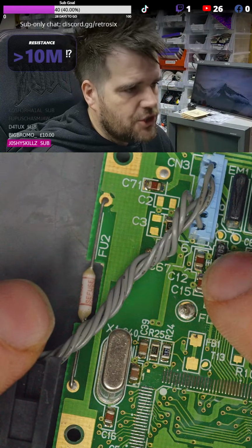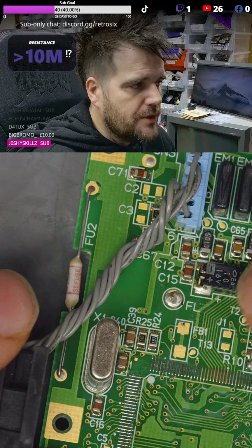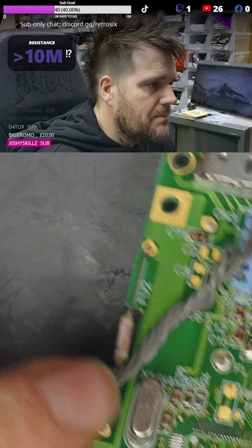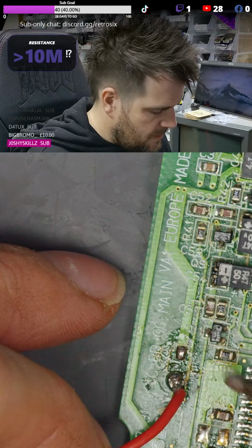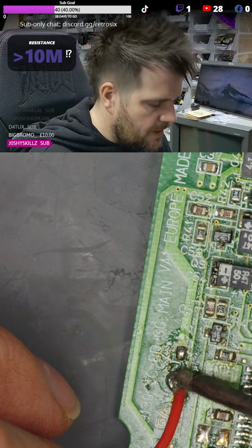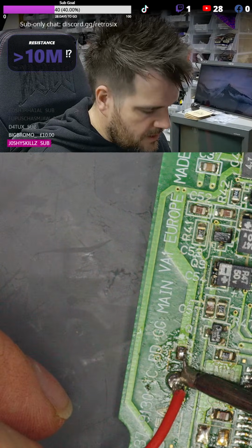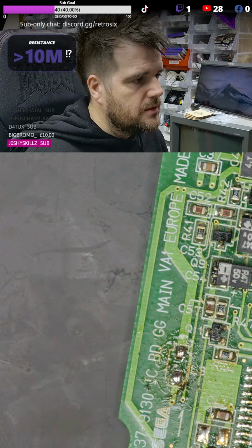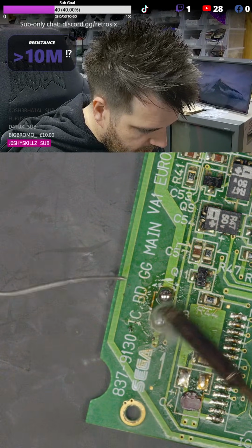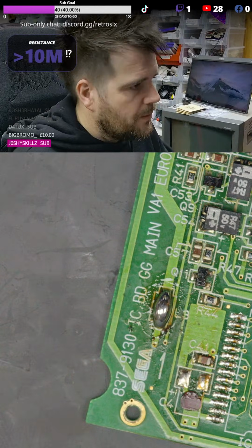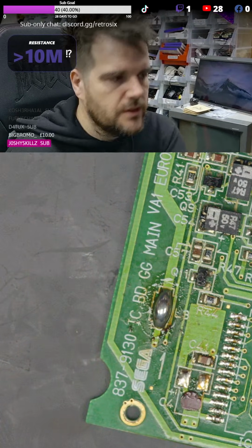If you don't have a dead short, though, thermals will almost always point you in the right direction. Just be mindful of things like the inductor getting hot. So I'll show you another example of another potential thing to look out for, a problem you should really be aware of. If I bridge this back, so I'm going to bypass the inductor, we don't really care for now, just put a giant bridge on. We've now got the short back on the board.